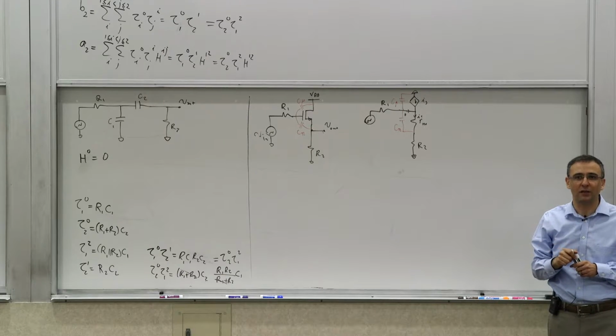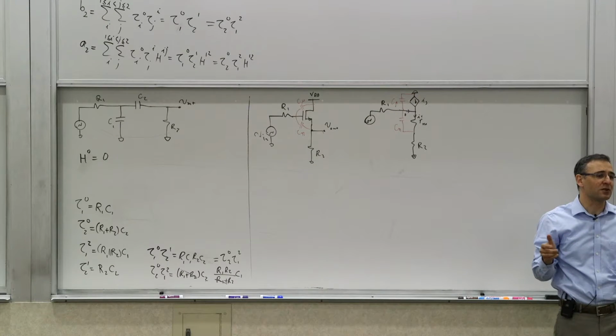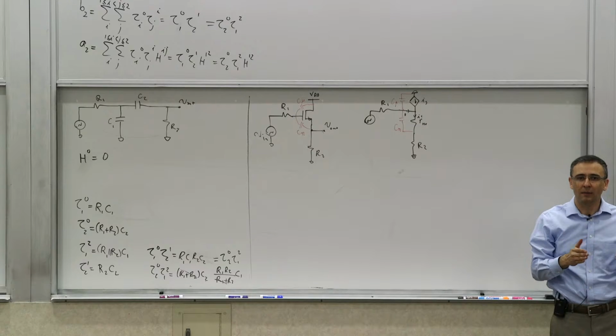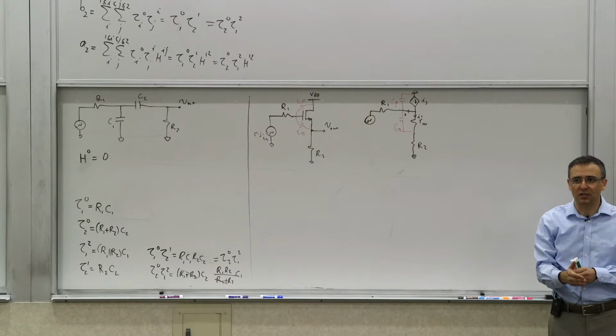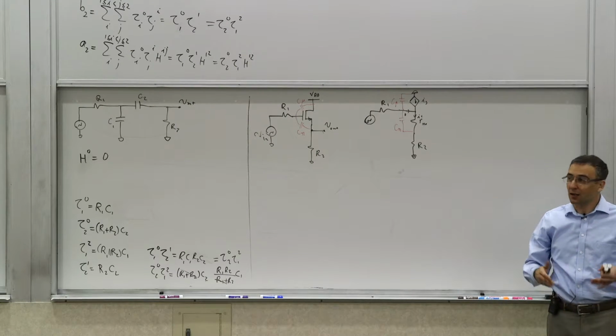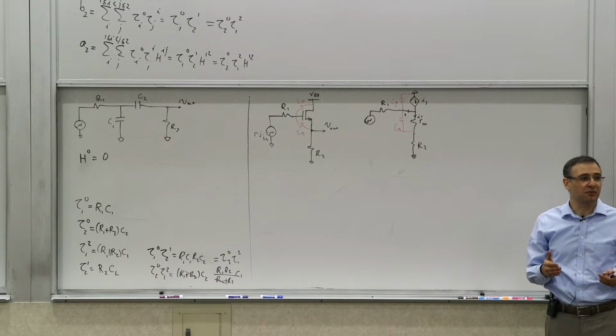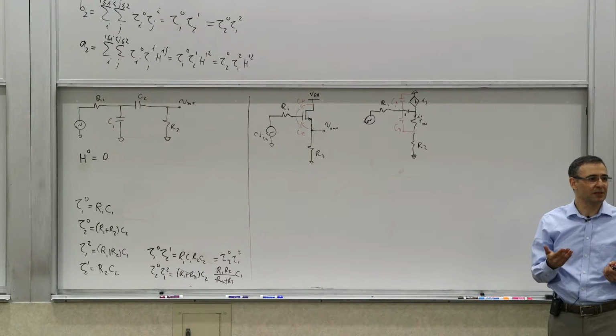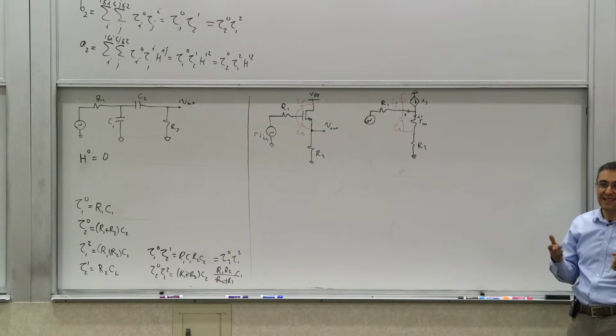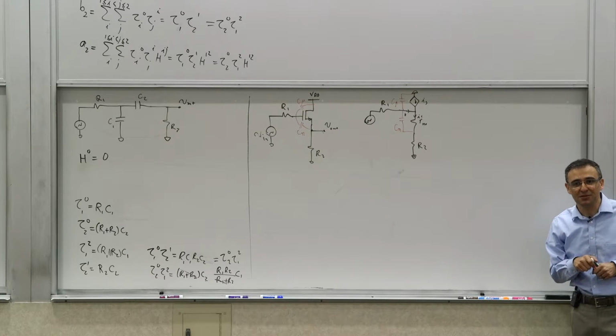Yeah, when you're checking for the loops, because all of the transfer functions we are writing, that's a good question, but the reason is that we are writing all the transfer functions in the small signal sense, because defining a transfer function for a large signal is technically meaningless, since it's a nonlinear system anyway. Writing a transfer function of that sort is meaningful for a linear system to begin with. There is something you can do for nonlinear systems, which